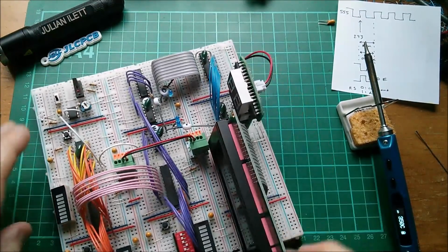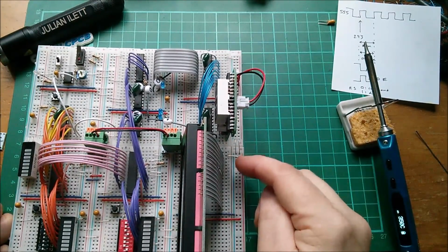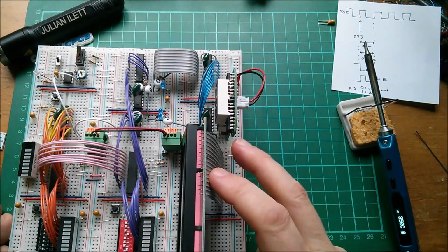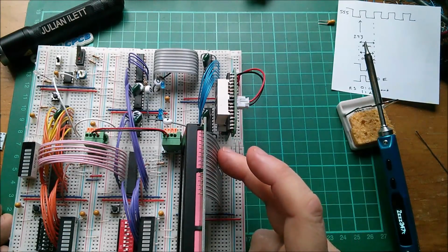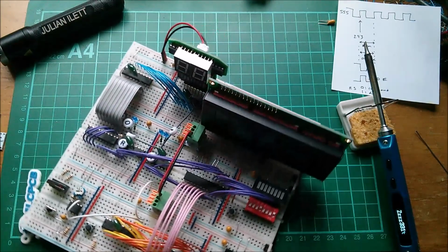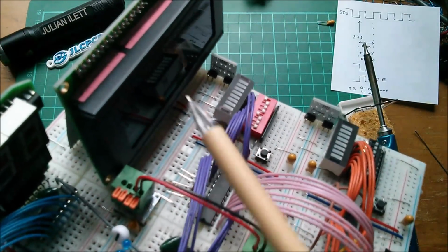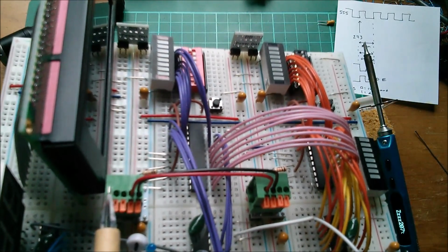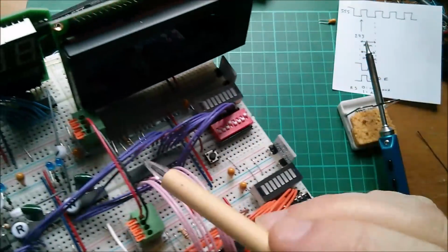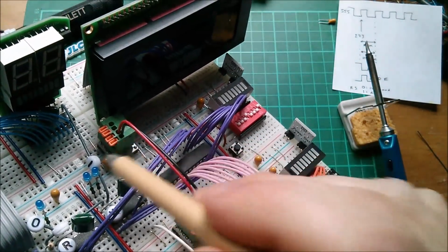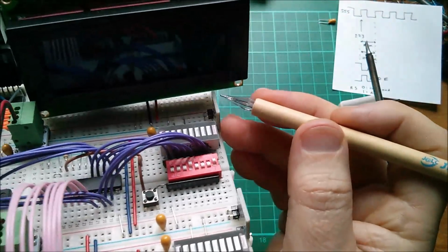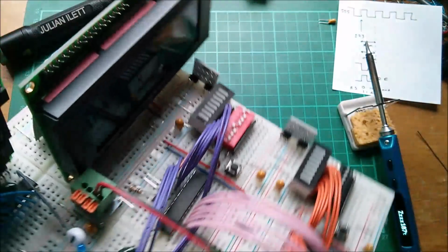So that's plugged in there, and now I can wire my VSS and VDD to plus and minus. Also the LED backlight, because I believe there was a resistor on the back of this board, so no resistor required. Let's get those done first. Oh, that's interesting. The display is tucked behind this connector here, which is holding it at a nice angle. And also you can see that these PCBs that I put to link the breadboards together, I've also used them vertically on the ends here, and the display is just sitting neatly behind that one.